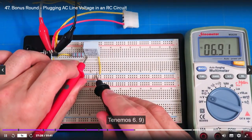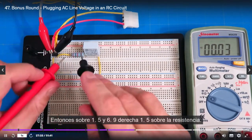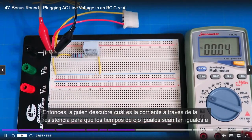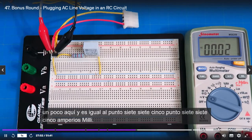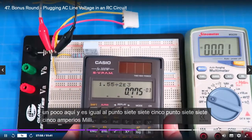Okay. And across our capacitor, what do we got? We got 6.9. So we got 1.5 and 6.9. All right, 1.5 over the resistor. All right, so someone figure out what the current through the resistor is. So V equals I times R, so I equals V over R. So we got 1.55 divided by 2K equals, and let me move this over on my calculator a little bit here, and it equals about 0.775 milliamps.